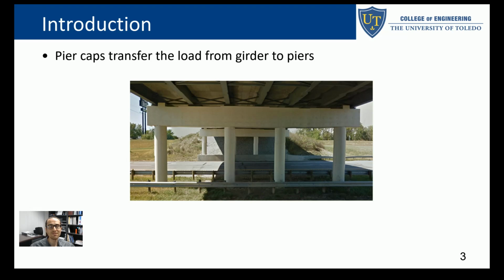Pier caps, we all are familiar with pier caps. They are transitional elements. They move point loads from girders to columns. It's an intermediate element. It's really important for the long-term performance of the bridge.